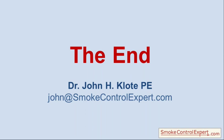The real fires in the world are not terribly repeatable, and you're sort of getting a general average answer when you're using CFAST, because it's based on these empirical equations, and there's a nice comfort about that. When you use FDS, you could make minor changes and get very big changes in your final answer.